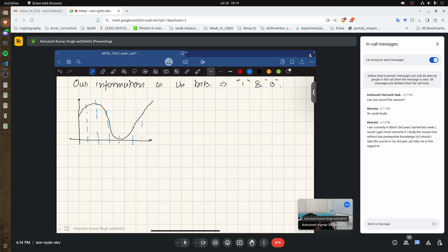One thing to note, the difference between the Nyquist theorem and here is that Nyquist was planning to faithfully recreate the same signal, whereas here I am only interested in the data logics. I'm only interested in the digital waveform here.